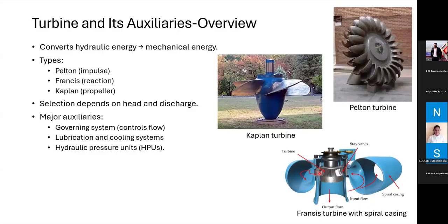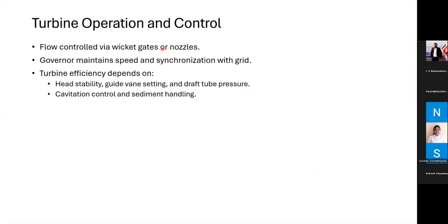So basically, when the water is flowing, or when the water is not stationary, it is the wicket gates or the nozzles that control the flow, not the main inlet valve, as I explained earlier. The wicket gates and nozzles are very dynamic devices, and they need to be properly maintained because they withstand high pressure as well as operate in a dynamic state.